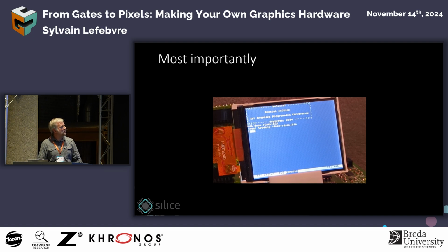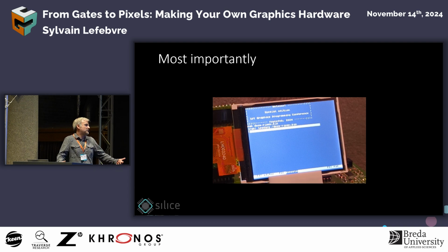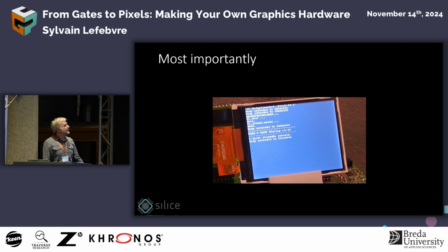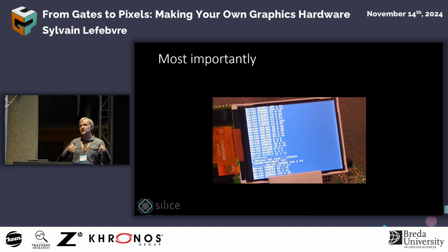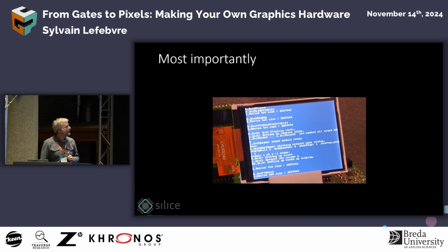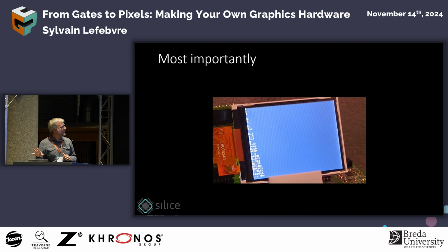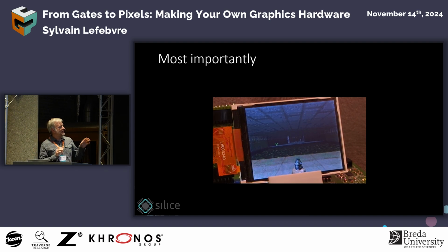And so here it's pulling the executable out of the SD card. This is a special port of Doom. It's a bit slow to load because I'm bitbanging the SD card. I just thought it would be fast enough. And now you have recognized the normal Doom startup. Now something different happens. This is the CPU extracting all the textures and all the sprites and sending them over to the GPU so that the GPU can fill the texture memory. There will be sound. I hope it's not too loud. Yeah, and then the game is starting.